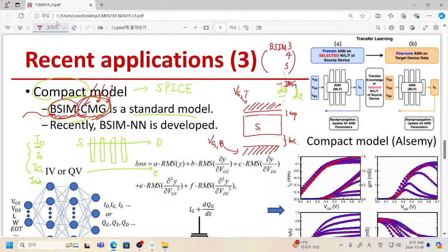They could be applied separately. For example, you apply a very low voltage to your bottom gate and only a high voltage to your top gate. That was possible. That's the reason why we have independent gate.